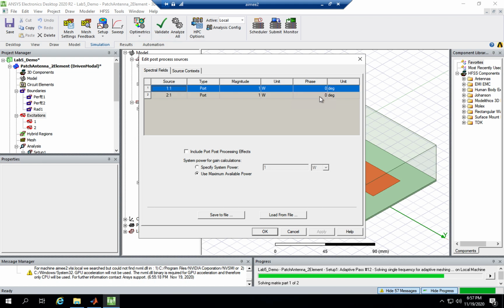Other than that, the report is fairly straightforward. Everything is in the report guidelines. In the discussion, I want you to discuss feeding techniques for antenna arrays. In this HFSS design, this is a fairly simplistic view of how arrays are fed. We just have 2 wave ports, and we can decide what phase or what magnitude we want to feed the ports.